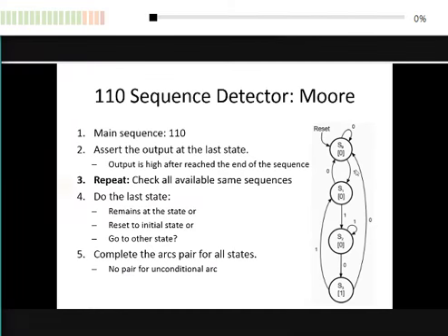And at S1, if we get the input as 0, we restart at S0. Why do we need to restart? Because whatever input 1 we found is not valid anymore. For example, if you find a sequence 1, 0, 1, 1, 0, 1, 1, 0, the first one is no longer valid. That's why when it's 0, you have to go back to S0.